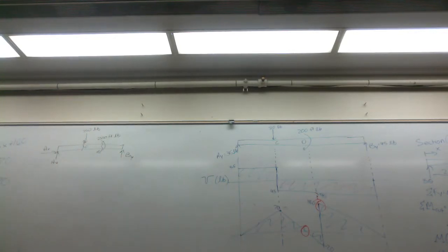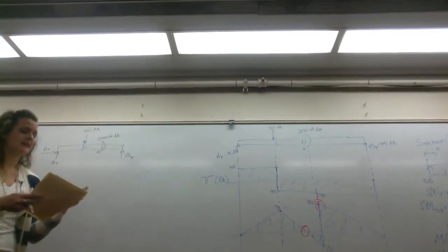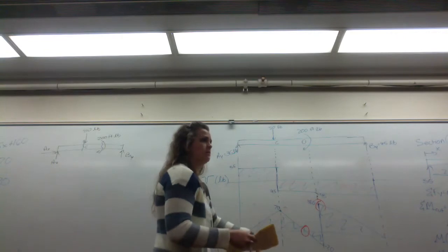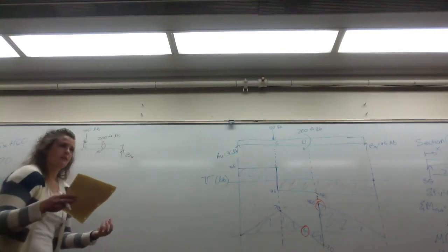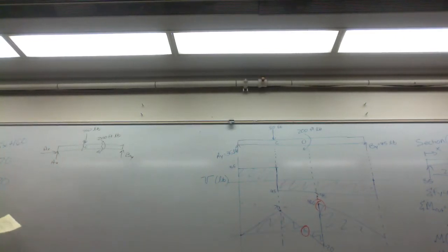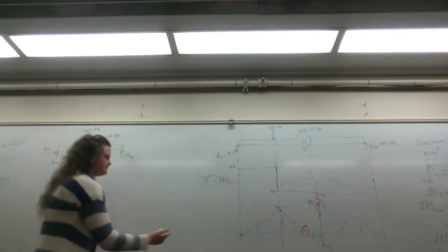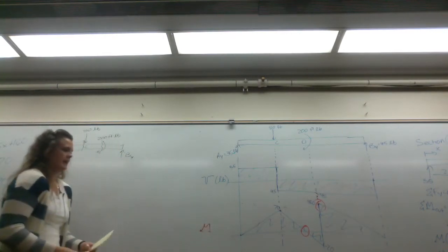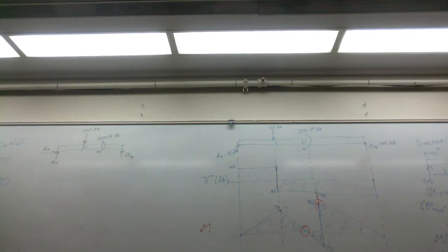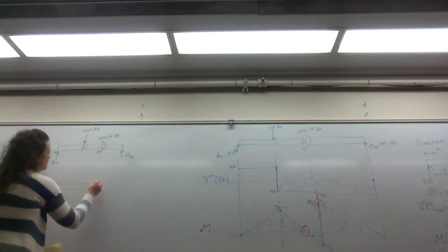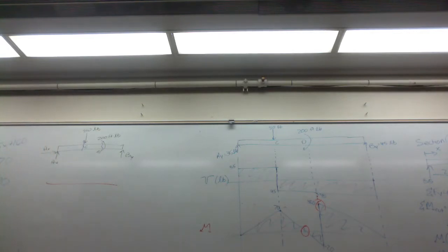Okay, so back to Jack's point, is it ironic that it's symmetrically loaded? It is, because we can represent how the beam's going to deflect. So how the beam's going to deflect, if we look at our bending moment, a positive bending moment does what to the beam? Go back to your sign convention of your internal forces. What's that? Concave up. So a positive bending moment.